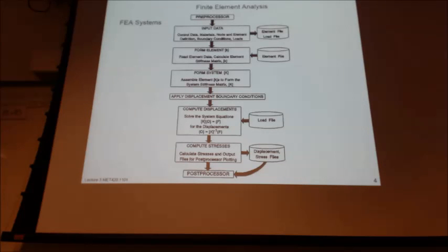So the process for doing this, and much of this will be masked by the software. When they first developed FEA, these were 3 separate software packages that you dealt with and transferred files between. There's a preprocessor, the processor, and the post-processor. So the preprocessor is putting the mesh together and working with the nodes and elements. The processor is then taking the forces and the loads and determining the displacement of those nodes for each element.